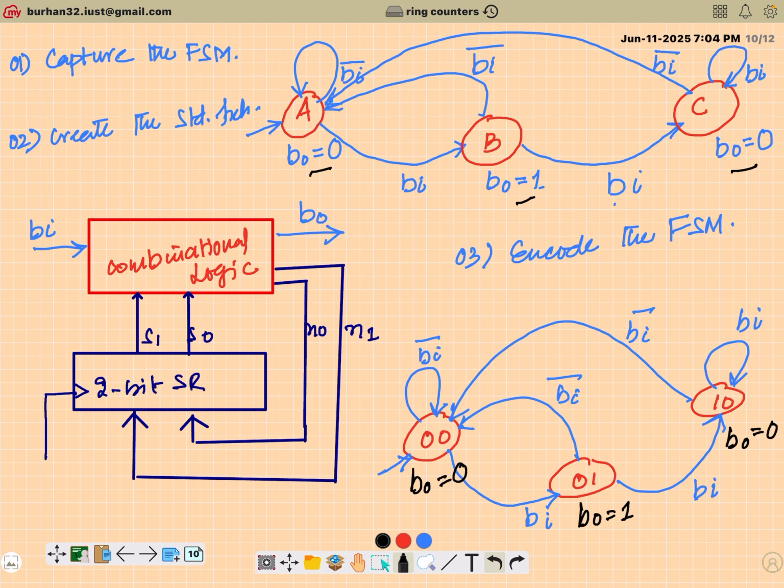And this was the way we captured it using the Moore machine, wherein we defined three states, A, B, and C. State A, the initial state, where the output is zero. And if you press the button, you will go to state B. If you don't press the button, you will continue to stay in the same state, which means in that case, output will continue at zero. But once you move to state B, output will be one. You will stay in state B for exactly one clock cycle. If you continue to press the button, you will move to state C, a new state. But if you release, you'll come back to state A. In state C, the output is zero. If you continue to press the button, you will stay in the same state. If you release the button, you will come back to state A.